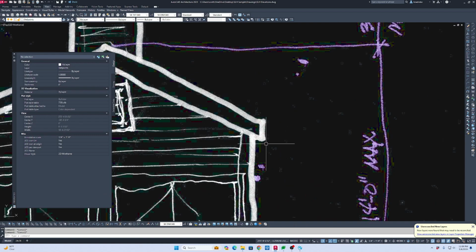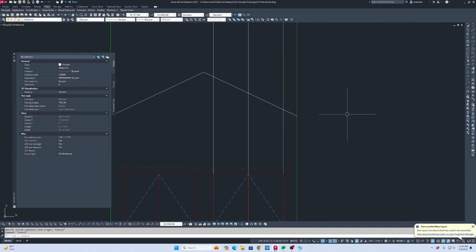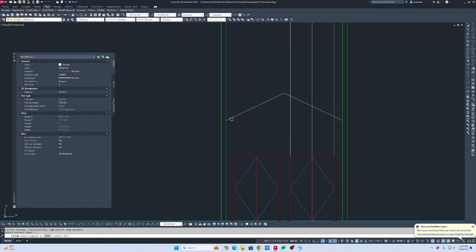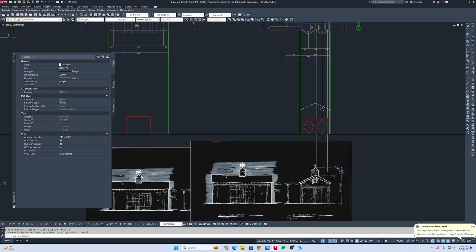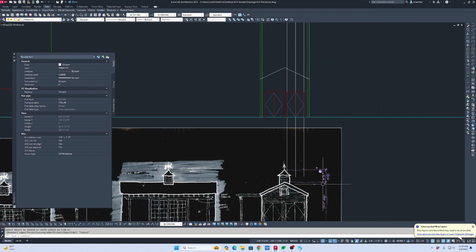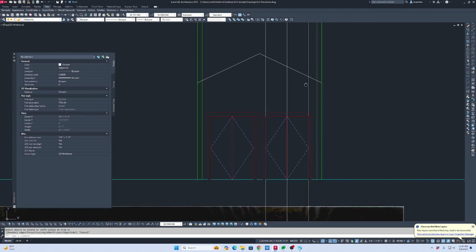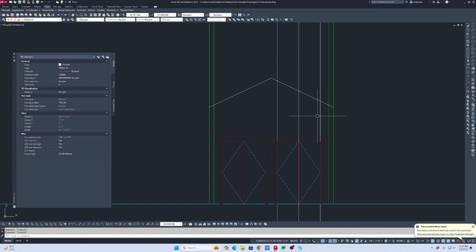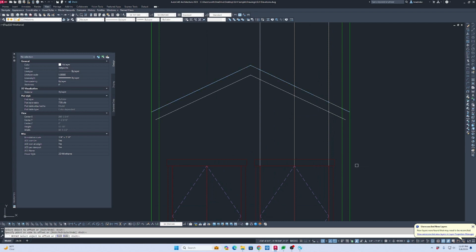So what do we have for an overhang? Not much. Let's say about 6 inches. And then we've got straight overhangs on these, plumb cuts. And what are we doing for, I'm going to do I think a 2x8 maybe? Let's try that. Oops, what's the offset? 7.25 is the real dimension for that. Yeah, I like that.